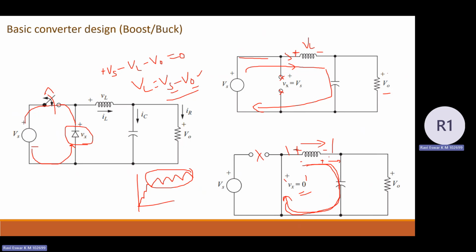To see that negative waveform, the negative polarity in the graph, I'm going to take a positive reference here, negative reference here. You can take a red wire here and a black wire here. Always, if you want to check the waveform across any element, you won't be changing at regular instance, right? You'll be connecting a red wire to one point and the black wire to the other point. So there you can check the waveform in the DSO. The same thing I am doing here: the positive polarity I am fixing here as a reference, and the negative polarity I am fixing here.